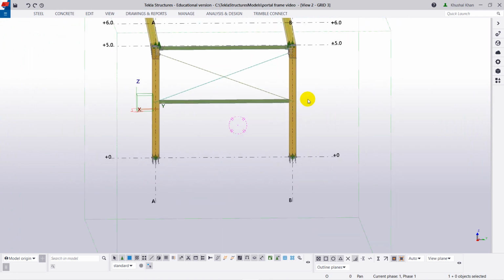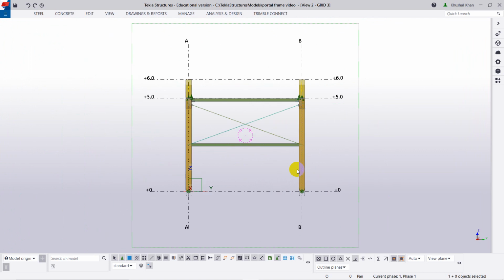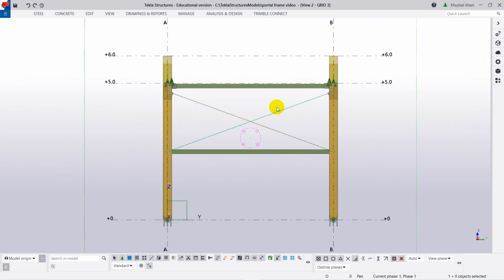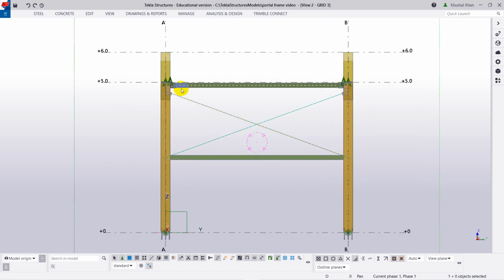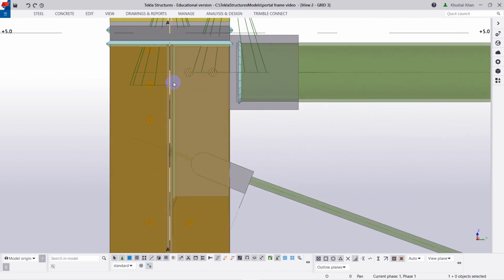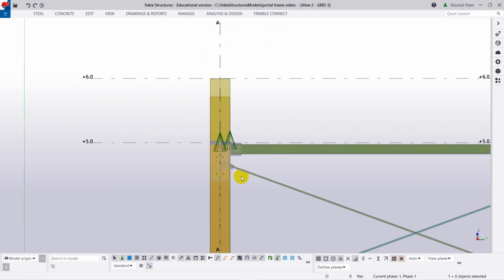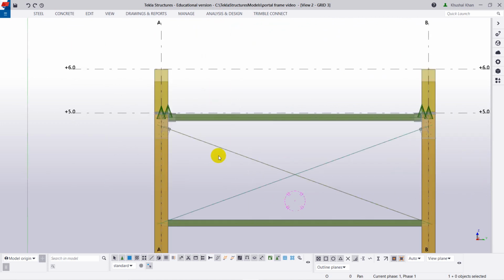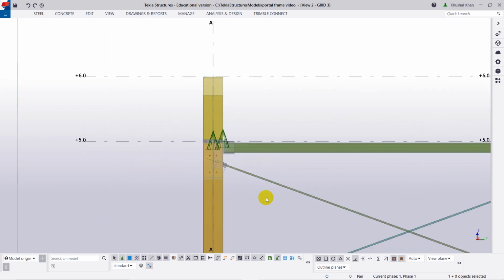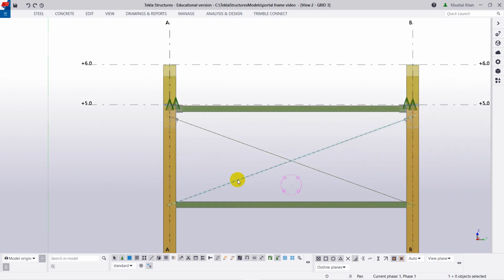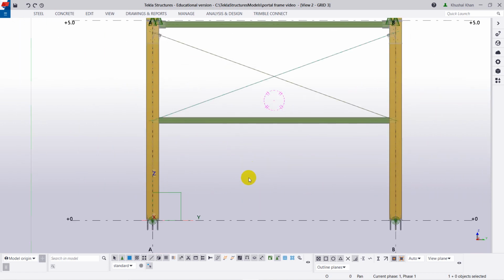So you should go to grid 1 and then press Control P for the plane view, and then Control 2 with a solid color, where we can see the lines of intersections for the column and the beam and everything. And Shift 4 for the light color for the joints. In this one we will just do the bracing.